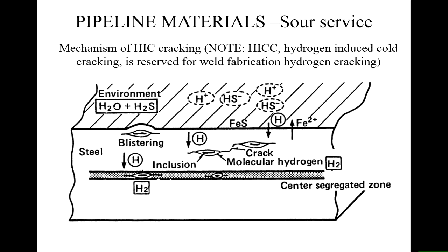And the reason for that is the hydrogen fits in the gap and it slightly affects the bonding around that gap. So the atoms are slightly weaker bonded, and then that will give you a higher chance that once a crack forms it will propagate through the material more easily.